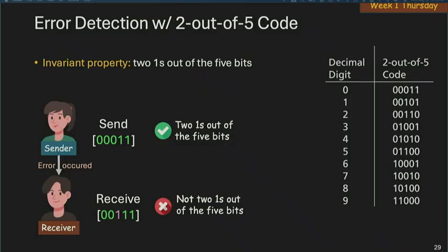You send me this. There's a 2-bit error. I receive this. There's no way for me to tell whether this is your original message or a message after 2-bit errors. This could be your original message because it's a valid 2 out of 5 message. This could be this message after a 2-bit error. I just have no way to tell.